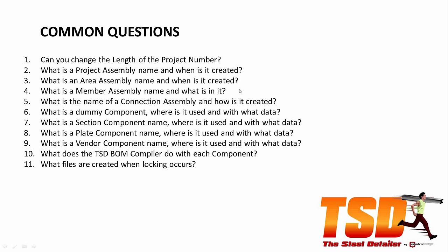Due to the SOLIDWORKS flexibility, we can put any numbers we want in there, but we've restricted it to 4 numbers, because if you follow certain systems, 4 digits is quite easy to use. You'd be lucky to do 9,999 projects within 1 year, probably even within a company's life cycle. However, 4 seems to work quite nicely.